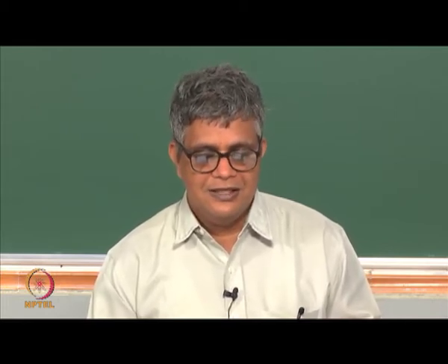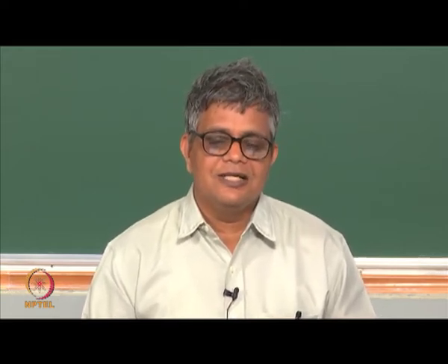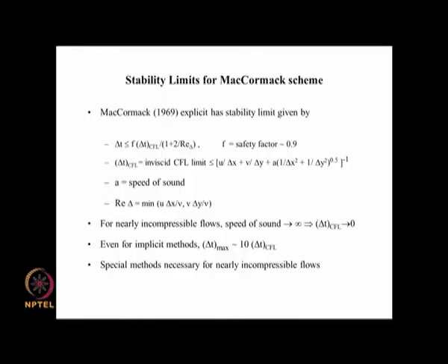And we have seen that these schemes are limited in their time step. In the case of the McCormack scheme, the delta t is a function of the speed of sound, and the speed of sound becomes very large for nearly incompressible flows and is infinite for totally incompressible flows where density does not change.